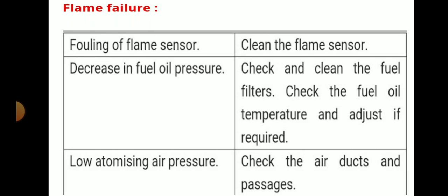Flame failure means fouling of the flame sensor, so clean the flame sensor. Decrease in fuel oil pressure means check and clean the fuel filter, and check the fuel oil temperature and adjust if required. Low atomizing air pressure means check the air duct and passage.